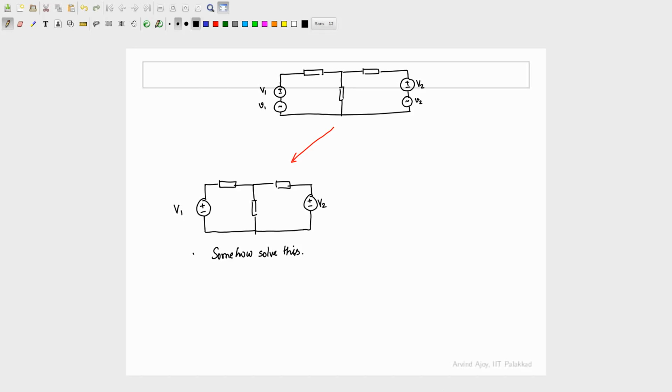Yeah, so in a sense what happens is that the sources in the typical amplifier are at DC, and you can make some very crude approximations for the transistor and actually come up with a solution for the nonlinear part of the circuit. In practice this is sometimes called the biasing circuit. So you somehow solve it. We'll see in subsequent classes how we can solve some special cases of these things, and this gives the operating point.